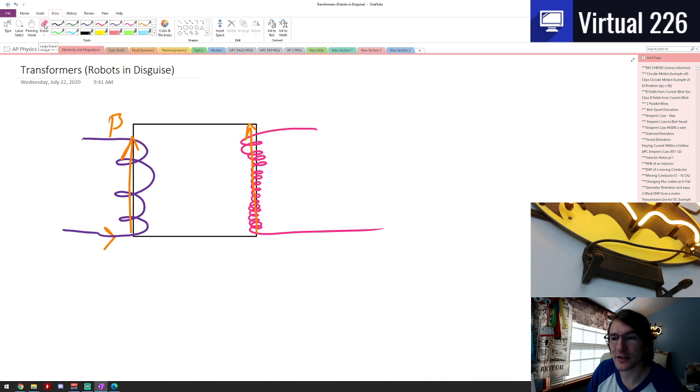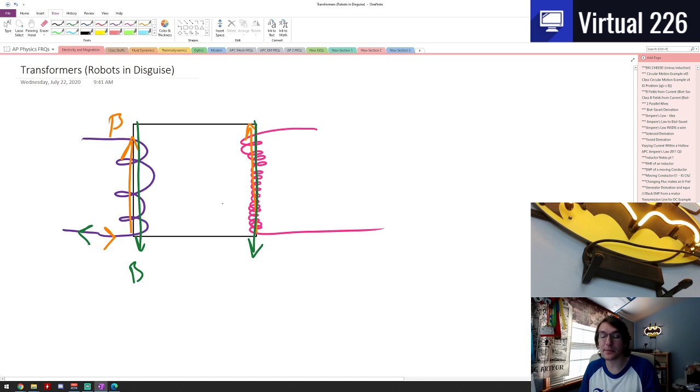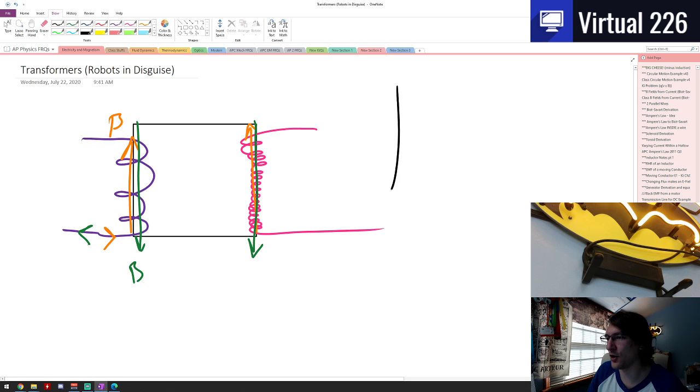But since we're alternating the current, the B field all of a sudden is going to flip because my current's going to go the other direction now, and when it happens, my B field flips to the other direction, which means, oh, look at that, my flux just changed again. And if we do this repeatedly, we're going to keep having a constant change of flux, and that will allow us to generate an EMF over and over and over again, okay? And we actually see this EMF as an alternating current.